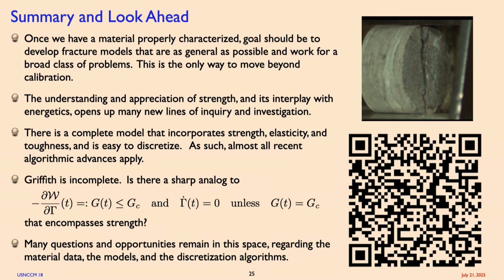Most quasi-brittle materials, particularly concretes, are used in applications where the material is confined. In any kind of confined quasi-brittle material, you always see some kind of post-peak softening due to pore collapse or micro crack, before they actually coalesce to a discrete fracture surface. How do you see this work extending into those types of applications?